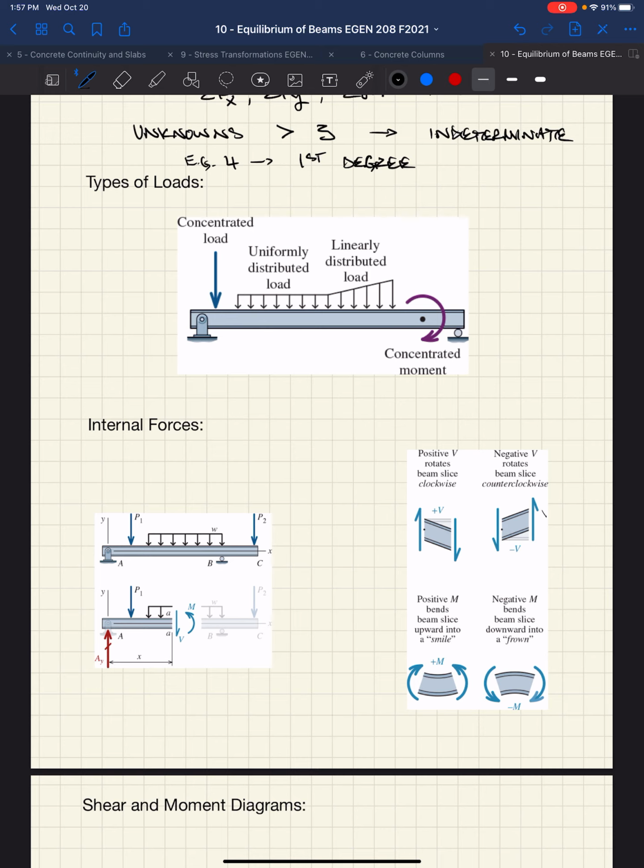In beams, we have a bunch of different loading types, right? As I mentioned, we're talking about loads that are typically perpendicular, or transverse, to the axis of a member, okay? So they can come in the form of a concentrated load. It's like you or I walking around. Uniformly distributed load, that's like the carpet on the floor, right? We've got a linearly distributed load, and I'm all talking about civil engineering because I think that's better, but snow loads, okay, haven't quite got enough snow yet, but snow loads, drifts are linearly distributed loads, okay?